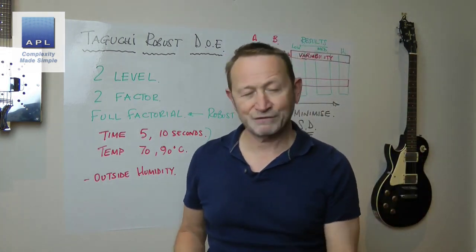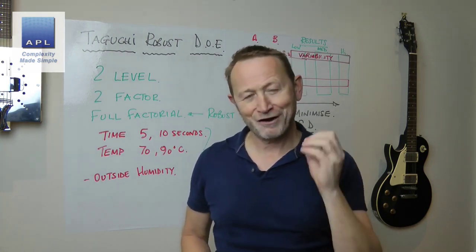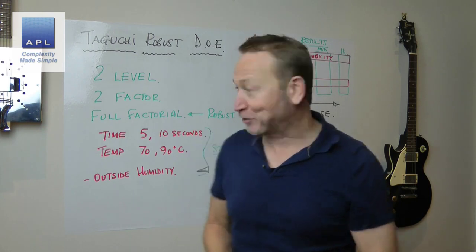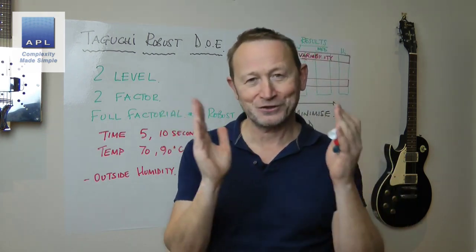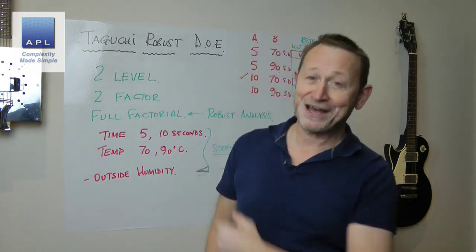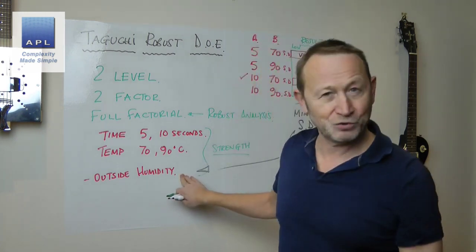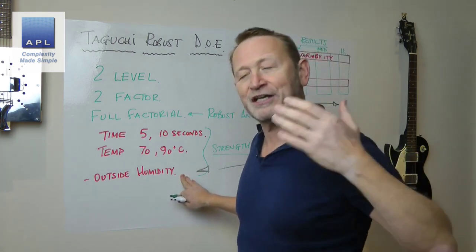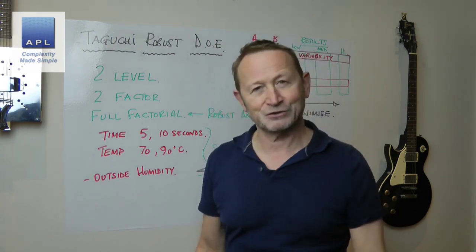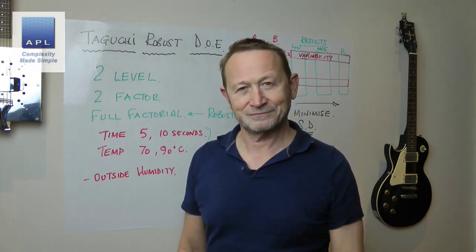I personally don't use a lot of what Taguchi did back in the day, but some of the things he gave us are simply genius and should always be added to any design of experiments, whether it's a full factorial, a fractional factorial, or whether it's a Taguchi design itself, because that is superb. And I've seen some exquisite designed experiments that have switched variables off. You can literally switch a variable off and make a process robust to external noise. That is robustness Taguchi's way.